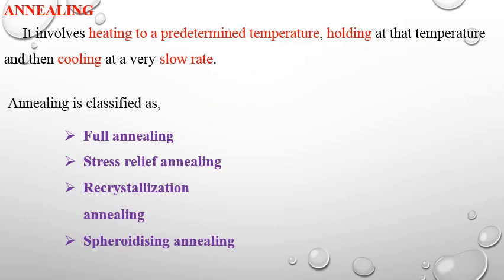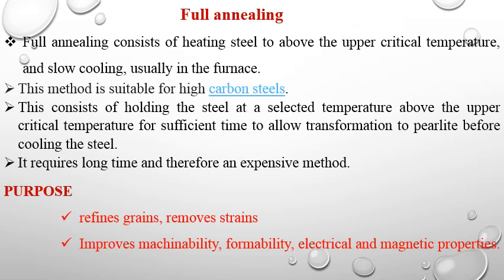Annealing involves heating to a predetermined temperature, holding at that temperature, and then cooling at very low rates. Annealing is classified as full annealing, stress relief annealing, recrystallization annealing, and spheroidizing annealing.